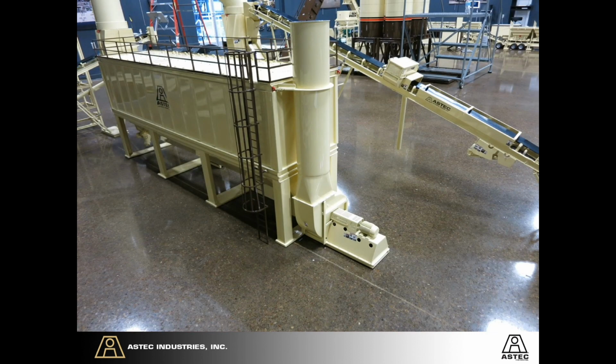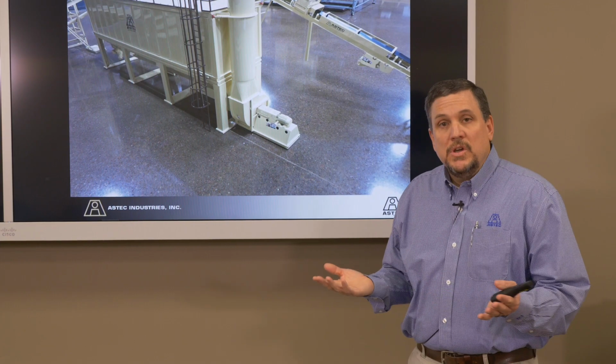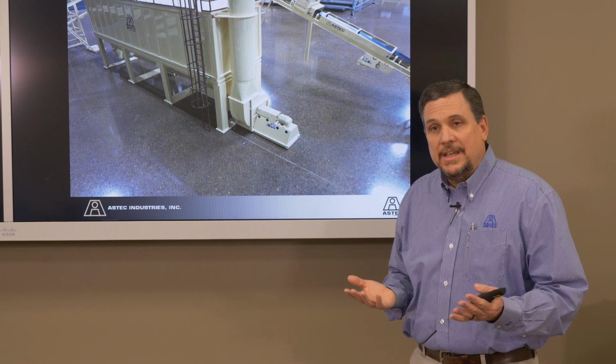There's a better view of the exhaust fan. Years ago, what we would deal with on the exhaust fan is that we would have a damper control on it. And those damper controls were basically located right at the top of the fan. And you could use a set of louvers to actually move that, or radial style louvers to do that. Everyone has moved away from that, and they went to VFDs.